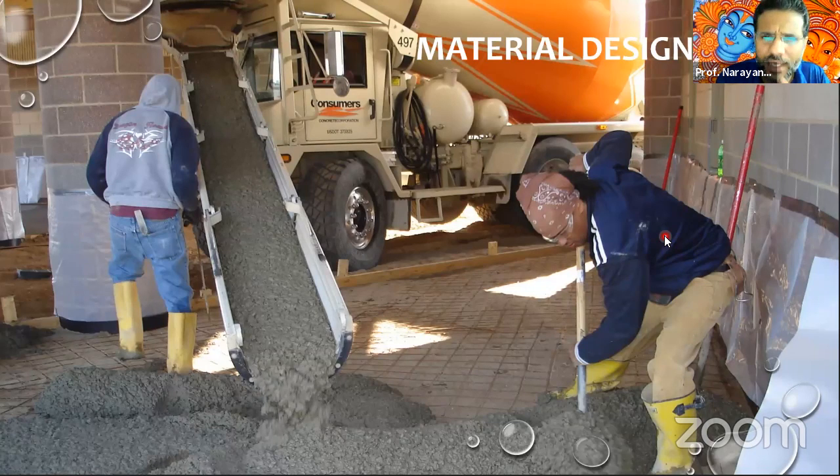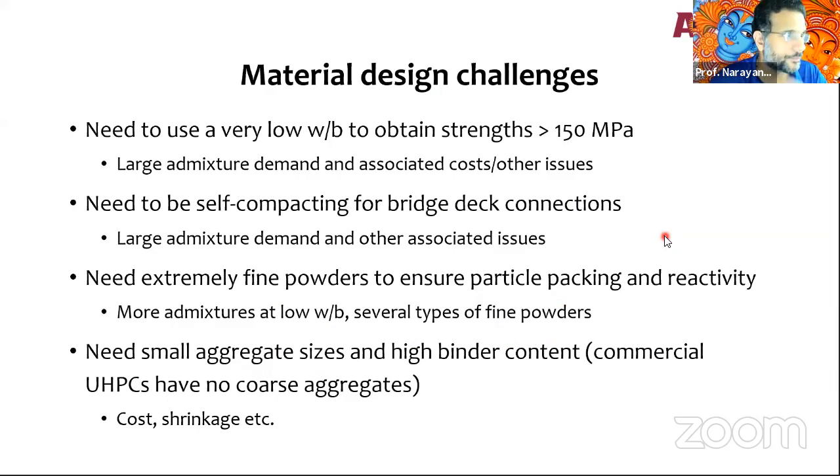But over the last 10, 15 years, our understanding of how we make concrete mixes has dramatically changed. And it's actually for the good, because sustainability was a big driver. We figured out that we cannot use the levels of cement that we have been using. 500, 600 kilograms of cement per cubic meter of concrete is no longer a possibility, but we still need the property. So how would we do it better?